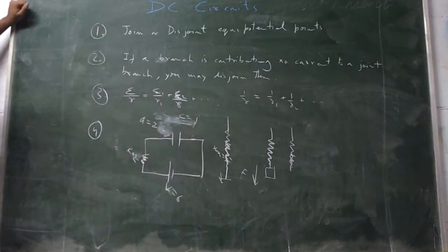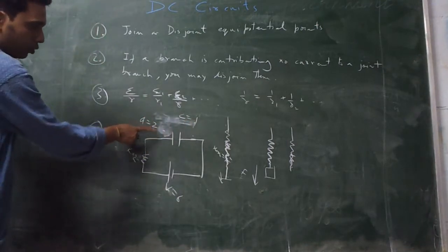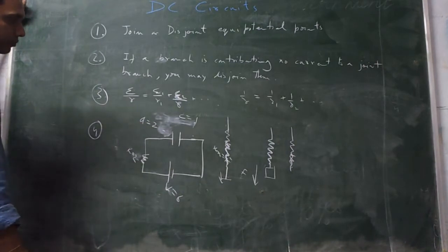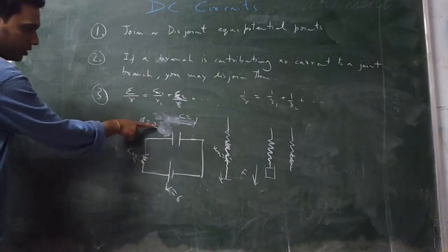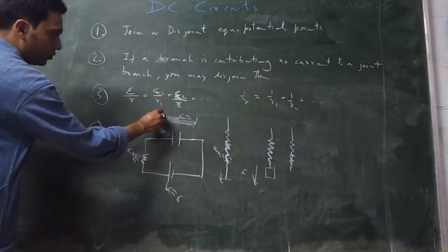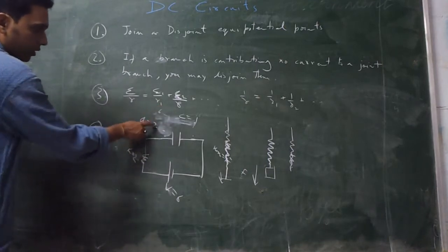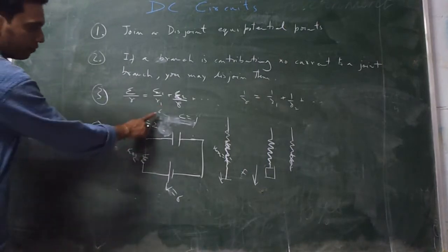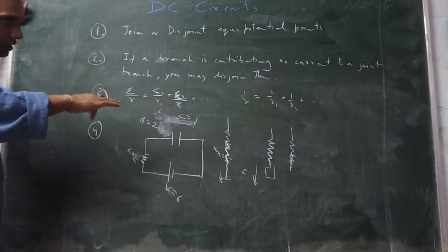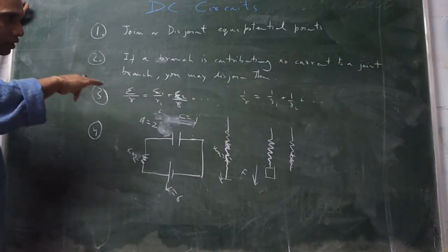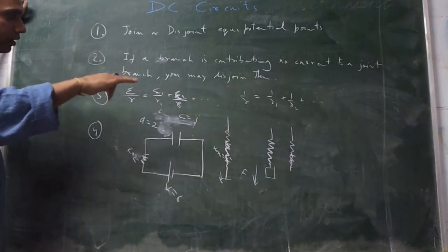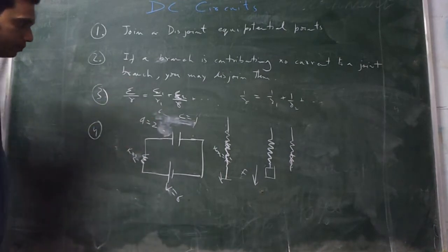Okay. Now it is going to charge from 2 to 6. Initially it is going to approach, there is a difference in what it wants to go to. It wants to go to 6 coulomb charge, it is at 2 coulomb charge, so it will go very fast, but as it approaches 6 it will charge very slowly and approach 6 in infinite time.